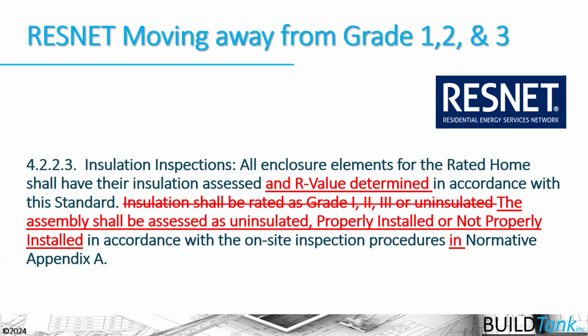The code, and manufacturers, are not able to tell you to install insulation kind of right, or with a little bit of defect. They basically have to tell you to install the insulation perfectly: no gaps, no voids, no compression. They can't tell you to install it with a little bit of compression. So the ResNet grading is going to move in that direction.